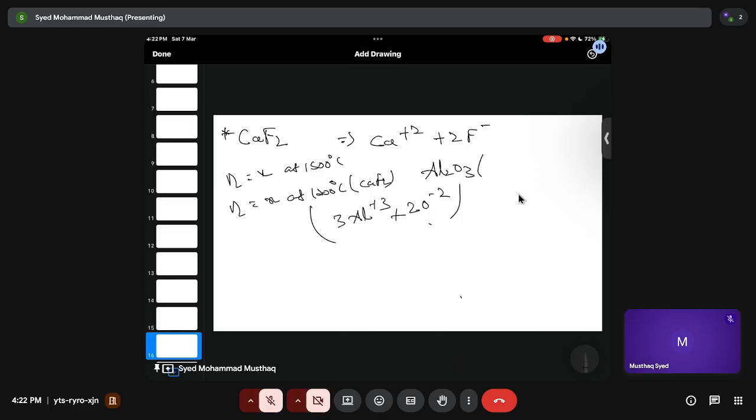Now that is about the viscosity. There are slag viscosity diagrams also, which can be easily understood because it's not very hard. You have the effect of temperature, and it's straightforward: when you increase the temperature, viscosity goes down. If you add some basic fluxes, that will further reduce your viscosity.